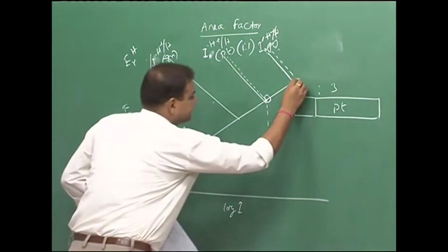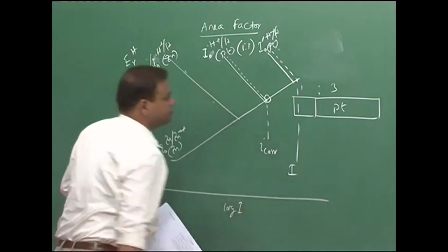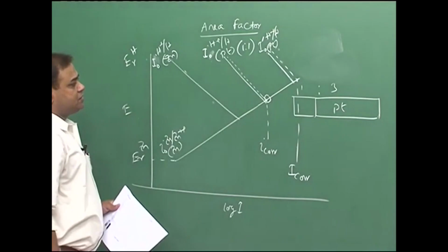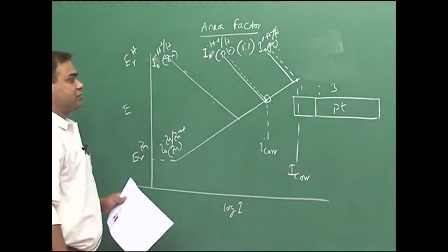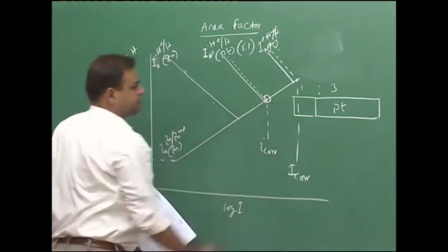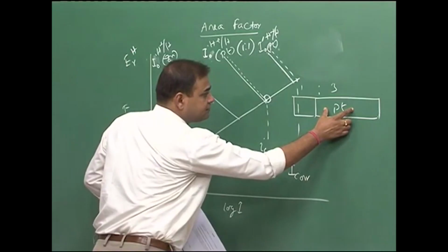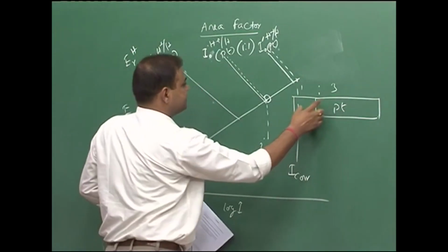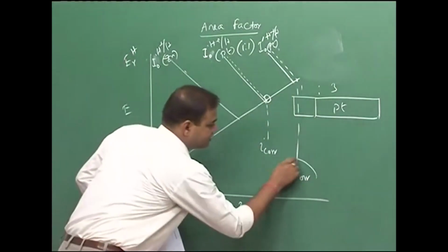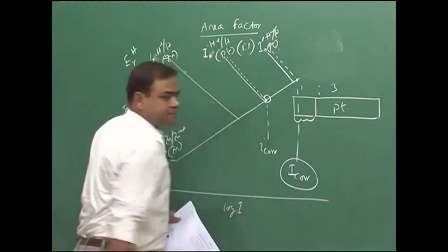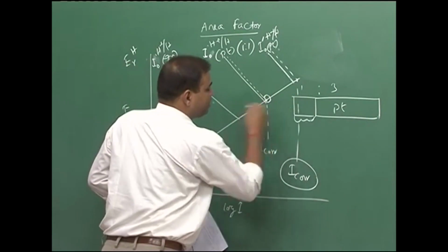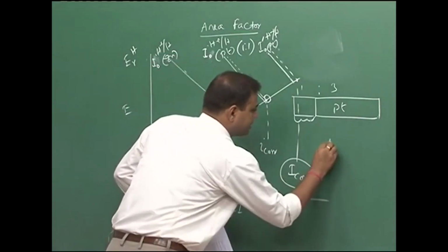So, now we see that the total current corresponding to the corrosion point increases with respect to this. So, if we increase the area of the cathodic part, we see that the corrosion rate on the zinc part would increase. Why? The same current will be felt by the small area zinc. So, if we increase the total current on the small area of zinc, then my current density